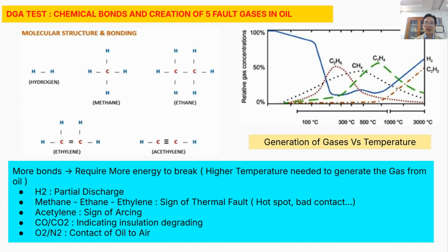Hydrogen may be generated because of some paint in the insulation under chemical reaction with additive and oil. However, the content of such generation is very small and stable. So a sudden increase of hydrogen always indicates something wrong with the transformer.